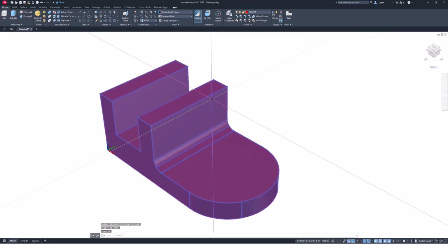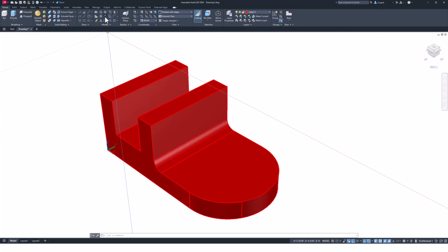I think what I want to do here is cut the circle opening through here. To do that, I am going to go back to my circle. This time I'm going to use center diameter. The center is going to be, if I hover over this arc, you see that little plus sign pop in there. I'll select this little plus sign for the center.